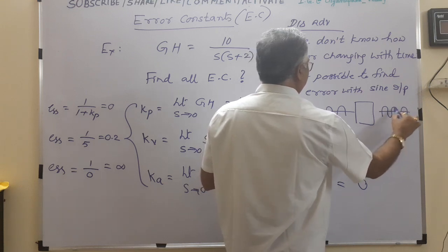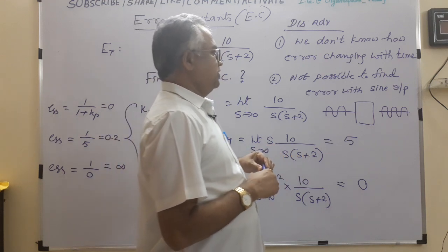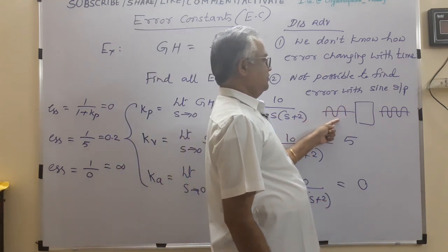What is the final value of steady state? Don't know. So the final value theorem is not applicable to a sine wave.